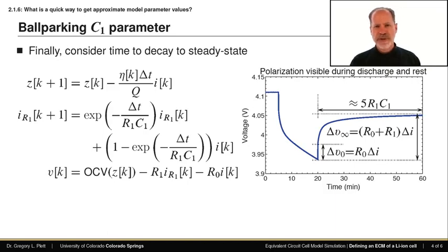And from linear circuit analysis, we can approximate, it's not perfect, but approximate, that the time it takes for a resistor capacitor circuit to reach a steady state value is about 5 time constants, or about 5 times R1 times C1. And we already know R1, and we can measure this time from this test, and from that we can deduce the quantity of C1.